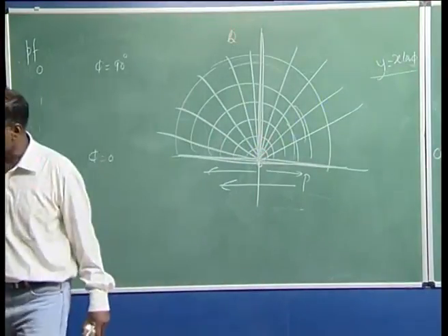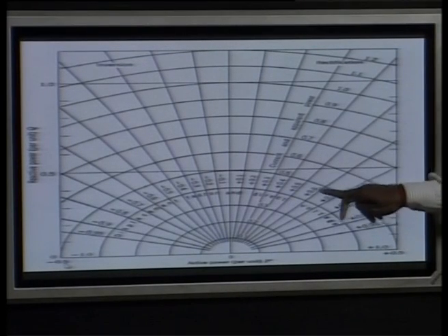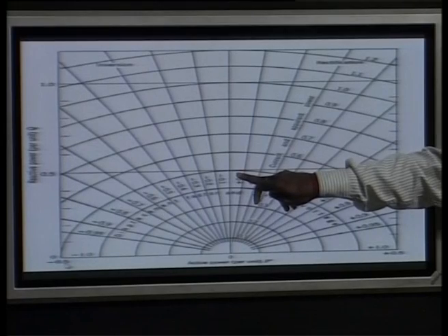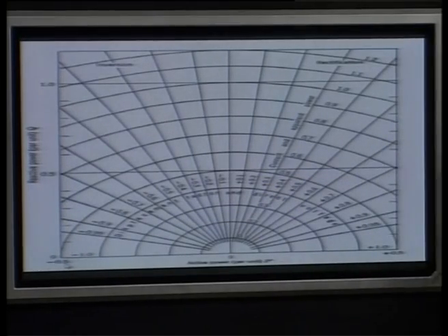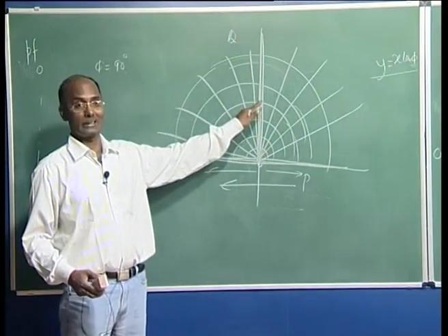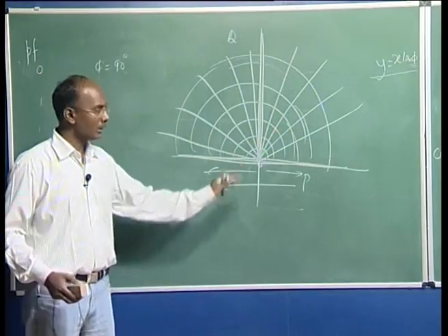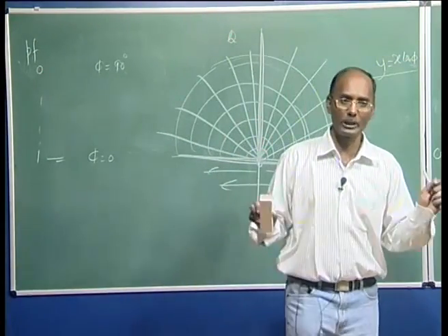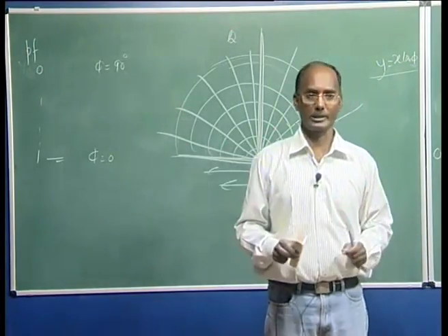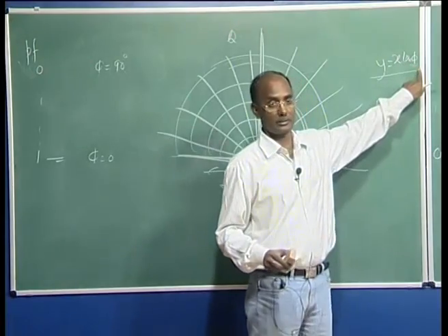You can see here the power factor is unity, and the power factor keeps on deteriorating till here 0, and then it goes to the lagging side, because power reversal is there, but the reactive power requirement is still there. So you mean displacement factor? Displacement factor, yeah. Here we are talking in terms of displacement factor, because the power factor is very difficult to calculate, because so many harmonics are there. So here we are still talking about this phi as the displacement factor.